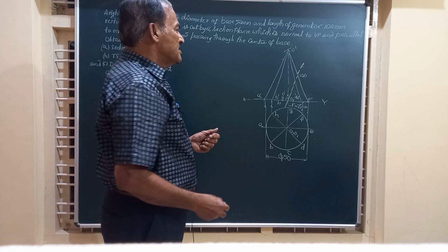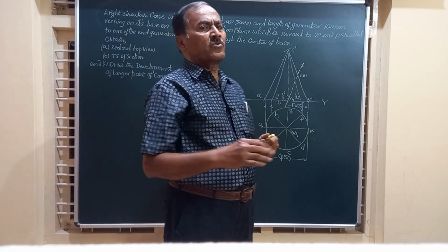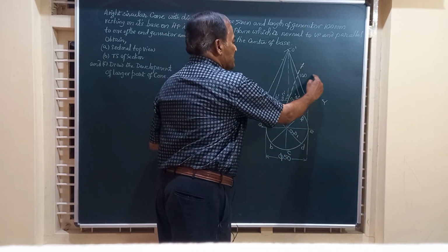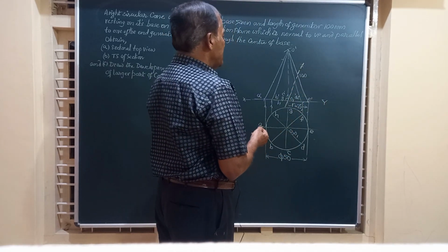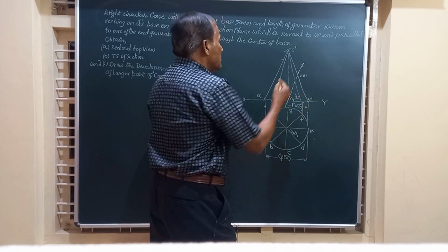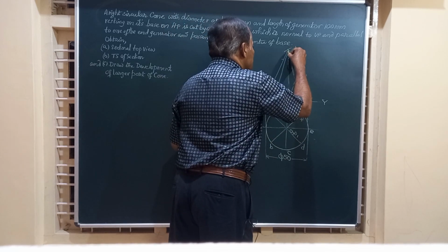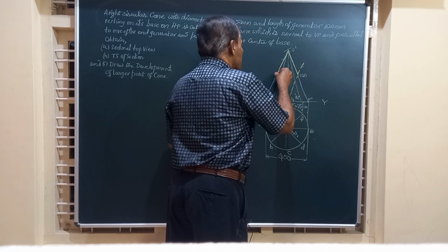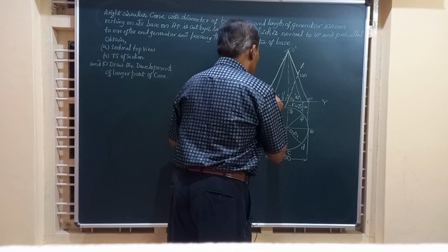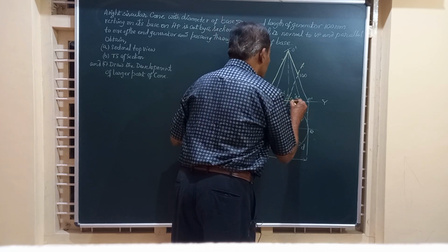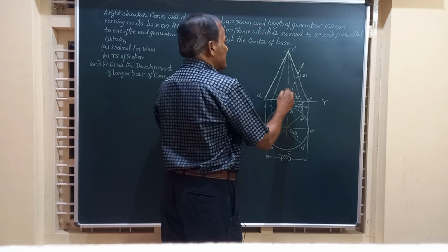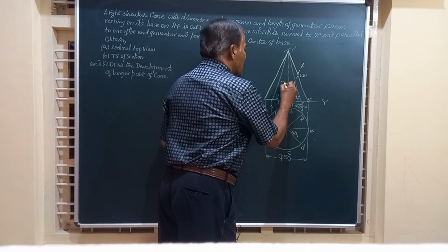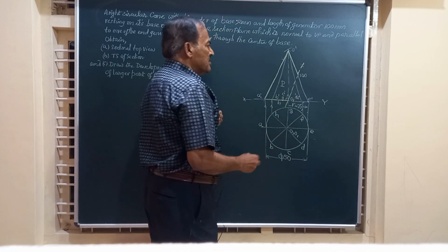And friends, if you are asked to find out what is the angle made by the section plane with the HP, you can measure this angle with HP. Now friends, after this is being cut, we are left with this portion of the solid. I will show it by visible lines. Only the bottom will show, and all the remaining will be shown by thin lines. So this is the part for which we need to draw the development later on.